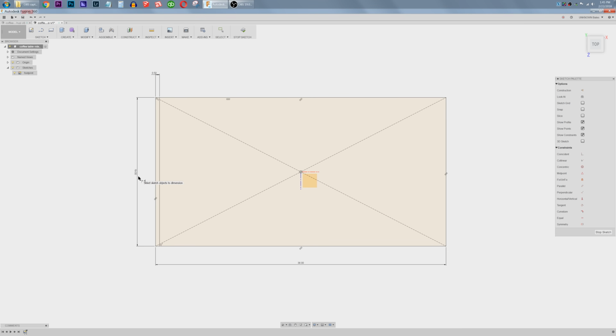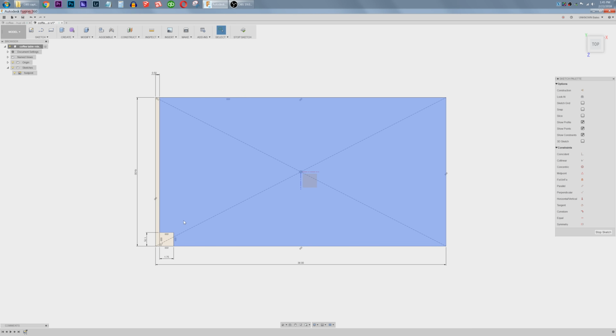That's my overhang. R for rectangle, and after the overhang, this is where my leg is going to be. 1.75, tab 1.75, enter. And again, you can set up parameters and all that for leg thickness or whatever. One rule in 3D modeling, as my dogs bark, is never draw what you can copy. It's always faster to mirror things, to copy things, to make rectangular patterns. Never draw what you can copy.